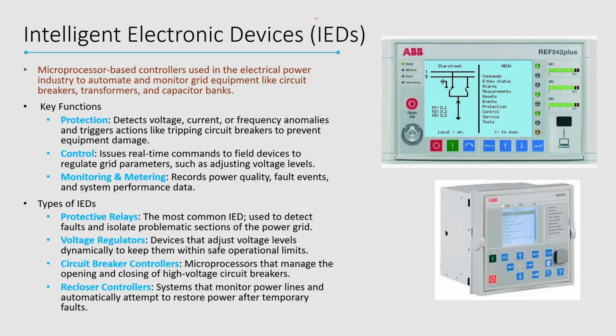So these devices could be the same old devices. For example, in all networks, you have these relays, and they basically operate by looking at the local voltages and currents. But you can now incorporate certain intelligence into these relays with the help of microprocessor-based controllers built into the protection relays. And so these are called intelligent electronic devices.